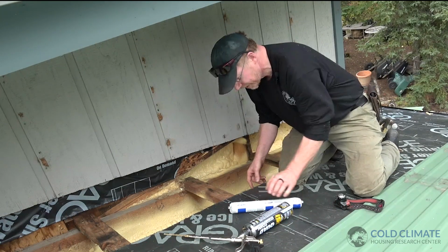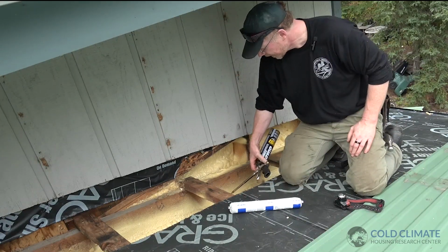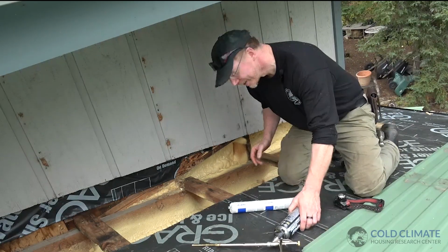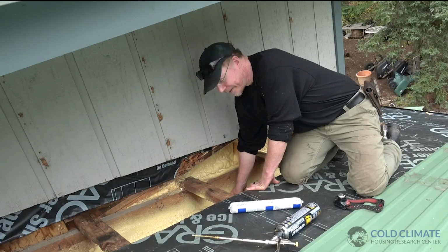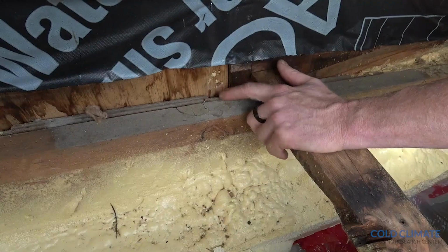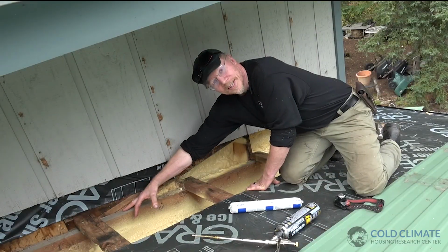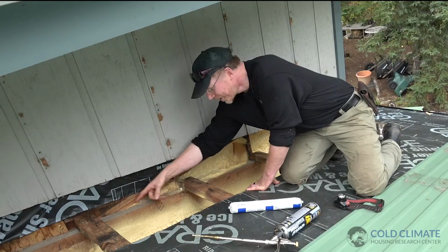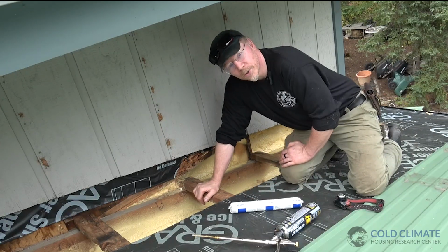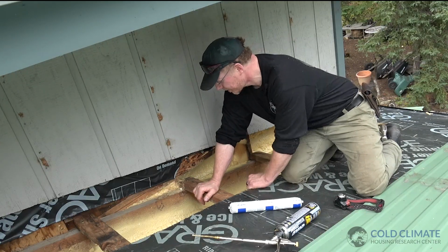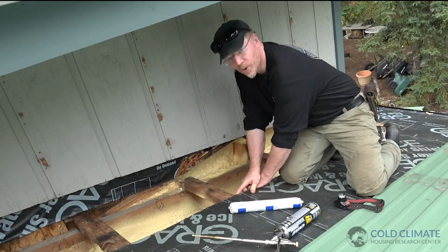And in order to do this, we're going to drill a series of 3/8 inch holes every 4 to 6 inches and inject minimal expanding foam here. The theory is that foam will expand and air seal right there at the pressure boundary. If we don't do that and we just air seal here along the top, we've still got this airspace here. It may be a dead airspace, but it still communicates, and indoor air can still get in there and condense because it will be cold. That, in theory, could lead to a future problem with dry rot. So I think in this case, an extra couple hours trying to air seal down at the bottom is well worthwhile.